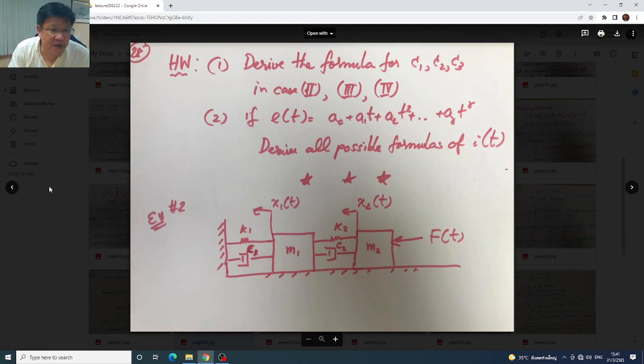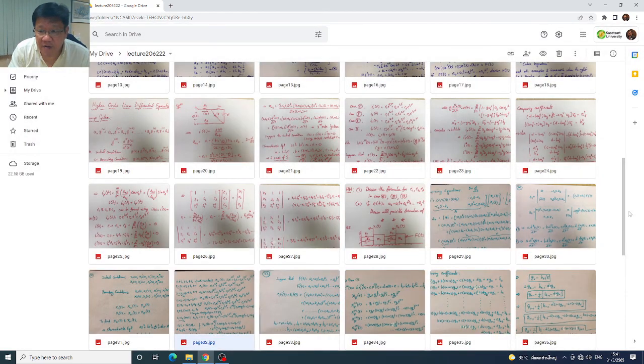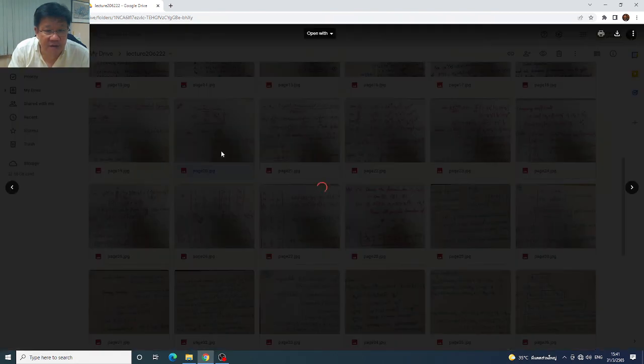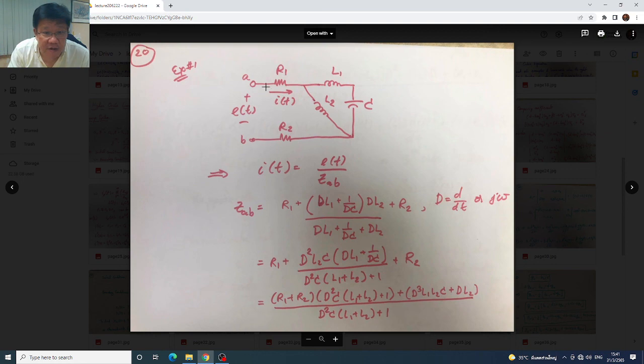The same as the electrical circuit system that I analyzed for you last time, which you might remember, this one. You know that if the electrical circuit has only resistors, it will be zero order. But once you add an inductor (L) or a capacitor, the order starts to increase. Like in this one, you have 2 inductors and 1 capacitor. That's why the resulting system becomes third order.